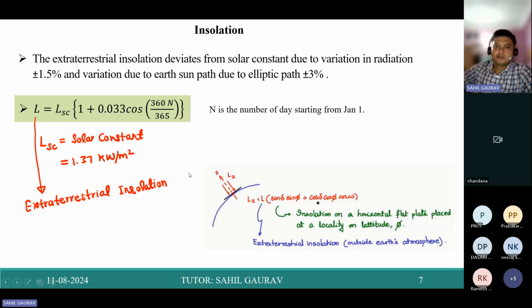So that means we have to put this protection diode across the module, not this PV cell. Okay, sir. So there are two: one is the forward diode for one cell, and the reverse diode for protection, sir. So what you are saying is the rating of the reverse diode, which is used for protection, shall be the summation of the forward diode and the output voltage. Is that so, sir?